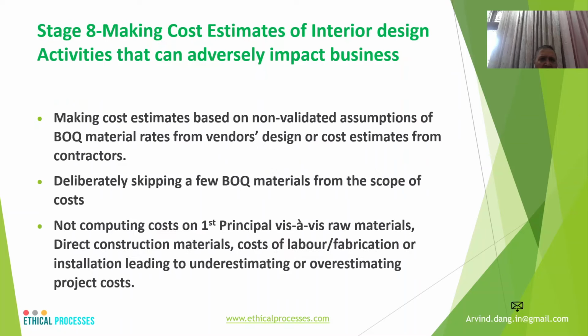Next one is the making of the cost estimates. Now here, instead of just giving a ballpark estimate that, okay, this is likely to be a total rupees cost per square feet, which is the easiest option, good practice is that one should have a detailed working of the costing based on the first principle of the raw materials or the direct construction materials, cost of labor, cost of fabrication, etc., instead of just going with a ballpark figure.